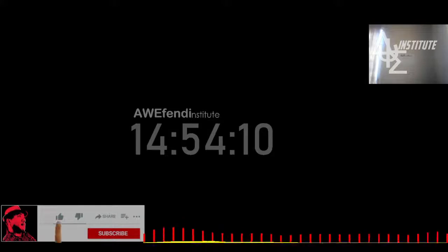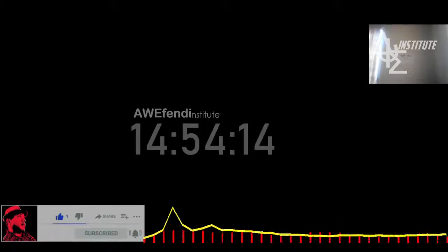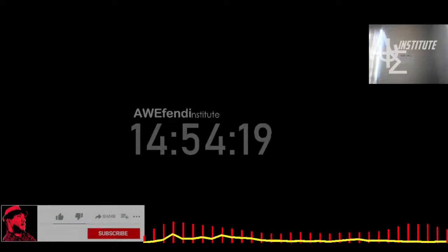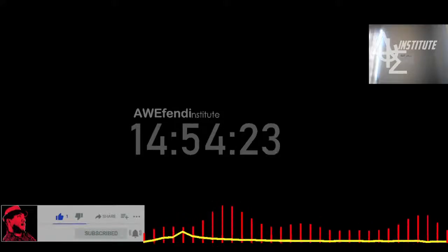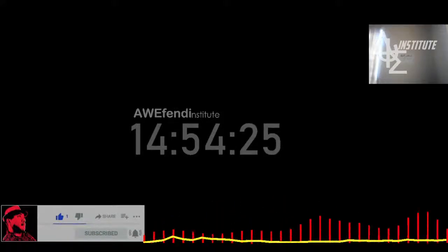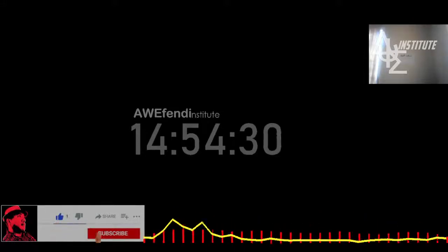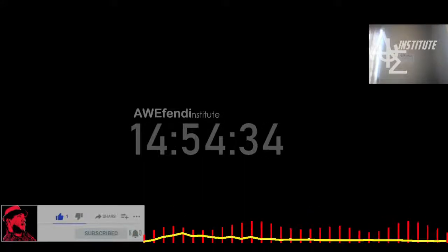So let's go another step. We changed the material. Another great feature that we have in Discovery is integrated geometry modeling. As Madhu was showing, we can make changes to the geometry live and see how this affects the simulation. Now, since the heat sink dissipates heat through convection, the bigger the convective surface, the bigger its ability to draw away heat.